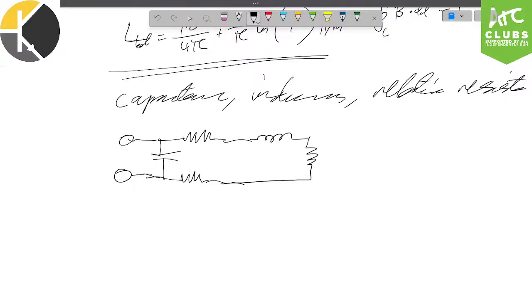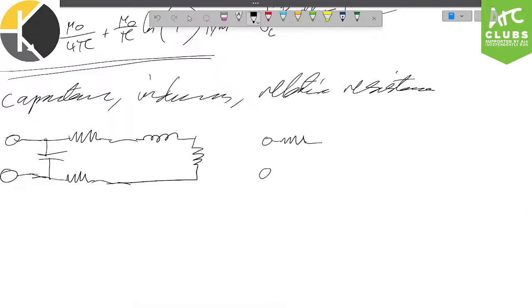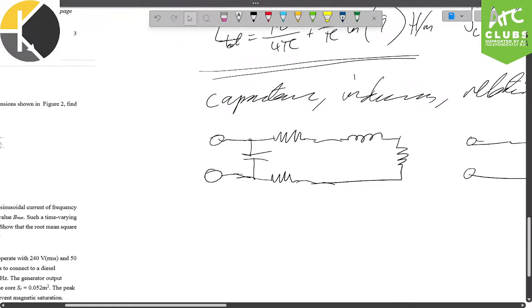This is how we do it in the high frequency model. In the high frequency model, just recall, you'll be able to see it potentially a little later. You have a resistance of the line followed by some manner of inductance through it, and then a capacitance to the other channel. And this scatters onwards until you hit your load resistance. Mind you, for lossless cables, we get rid of this resistor, and that's that. That's our approximation. That's how we get characteristic impedances and such. Let's move away from that, because that is high frequency. This is what it should look like.